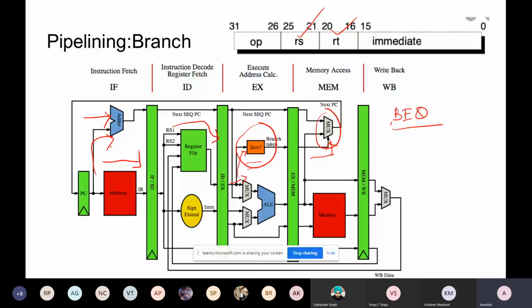address. So this PC, first let's consider as of now some offset value, based on how you have designed your memory. It may be anything. So based on whatever offset you have given, PC plus this offset value gives the immediate next sequence address, the immediate next instruction address in your instruction memory. That means if there is no concept of branching, there is no concept of jumping, then you will just go to the next instruction. So this is the next instruction coming to this mux.